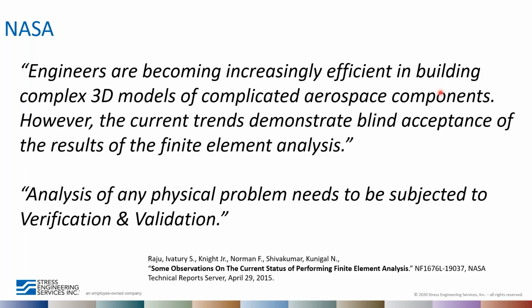And there's a paper by NASA on observations of the current status of performing FEA that says engineers are becoming increasingly efficient in building complex 3D models of complicated aerospace, or really any types of components. However, the current trends demonstrate blind acceptance of the results of the finite element analysis. And it goes on to say, analysis of any physical problem needs to be subjected to verification and validation.